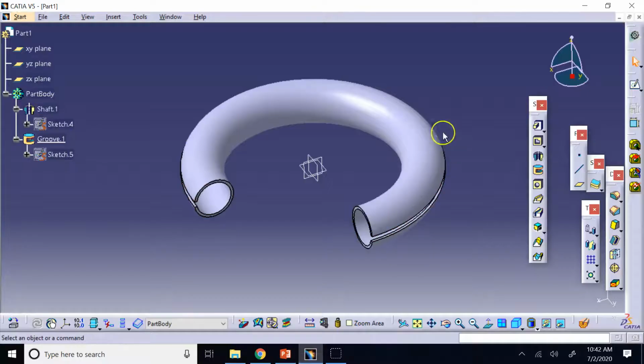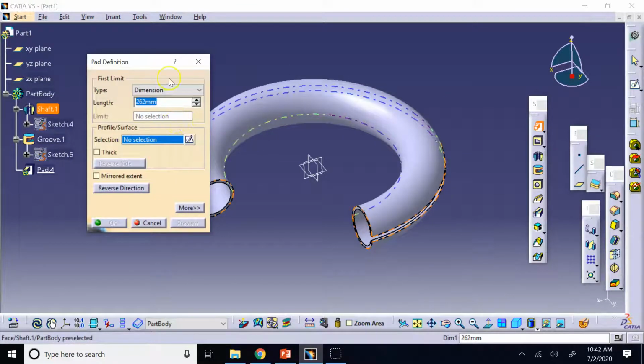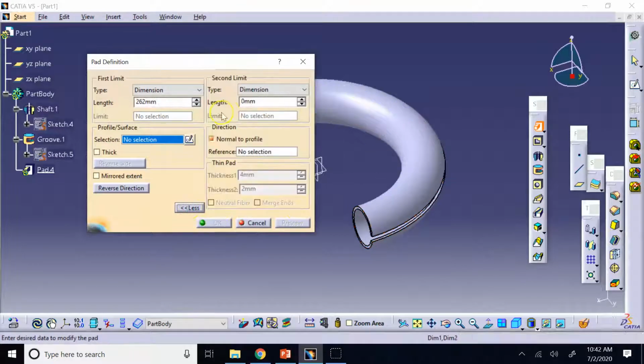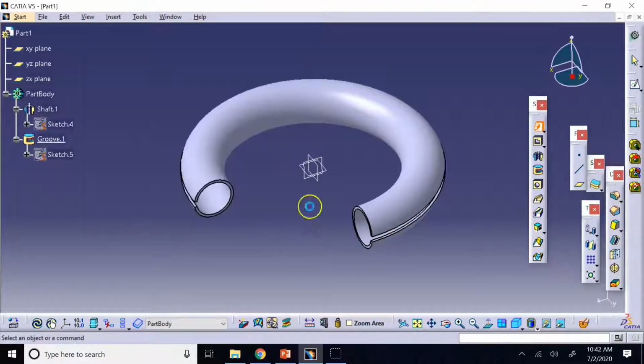And the thing is, the simple extrude that we have, the simple pad command that we have, there is nowhere in it that you can also provide a draft angle. So you cannot do it with this extrude. But if you expand this guy, there is another version of it, and there is another version of it. These two versions are quite interesting. Drafted, filleted pad, and multi-pad. Okay, so I'm going to explain them in a second.